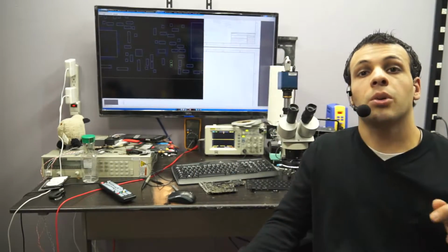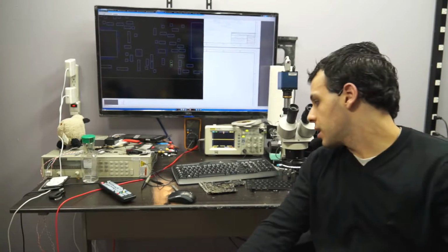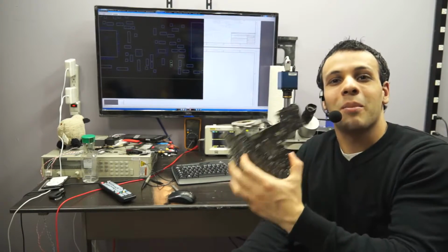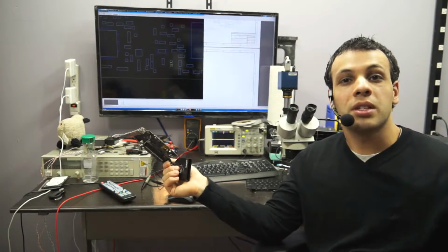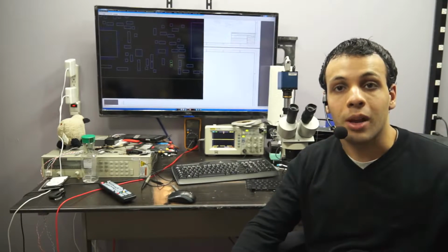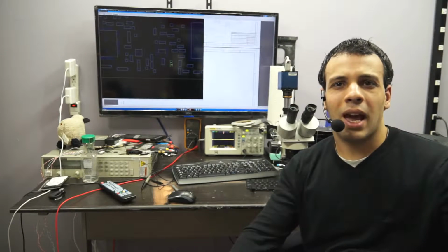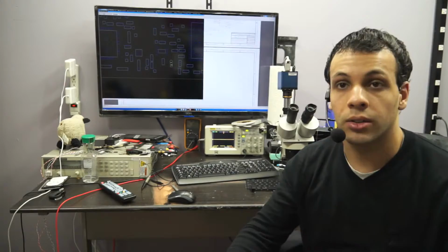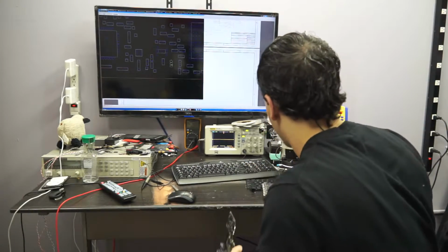But it's not BGA rework once. It's where I'm going to have to do BGA rework 2 or 3 or 4 or 5 times. Because a lot of these boards over here that get thrown away, they get thrown away because of a bad SMC. You can't just buy an SMC and put it on the board. You have to take it off of another board because it comes with programming, and it's a chip that cannot be programmed simply. So it's going to be about an hour, 2 hours of me just sitting here and cursing, doing the same thing over and over again. There's truly no reason for me to include that on camera, because that really is not beneficial to you.